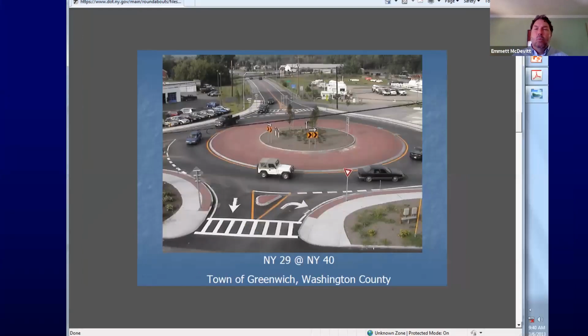Compare and contrast that with a conventional intersection. We've had 2 fatalities at roundabouts over 10 to 20 years, period. How many fatalities would we have with conventional intersections with those same 200 over a 20-year period? Or even serious injuries. Now, I don't have the stats for serious injuries, but if it's consistent with the other stats throughout the state and throughout the world, we know that roundabouts reduce crashes by about 50 to 70%. And ostensibly, the severity of the crashes are significantly decreased because you're diverting that traffic and not hitting them at right angles.